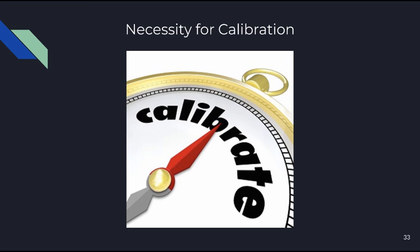When this situation is reached, it is necessary to recalibrate the instrument back to the standard specifications. Such calibration is performed by adjusting the instrument at each point in its output range until its output readings are the same as those of a second standard instrument to which the same inputs are applied. The second instrument is one kept solely for calibration purposes, whose specifications are accurately known.